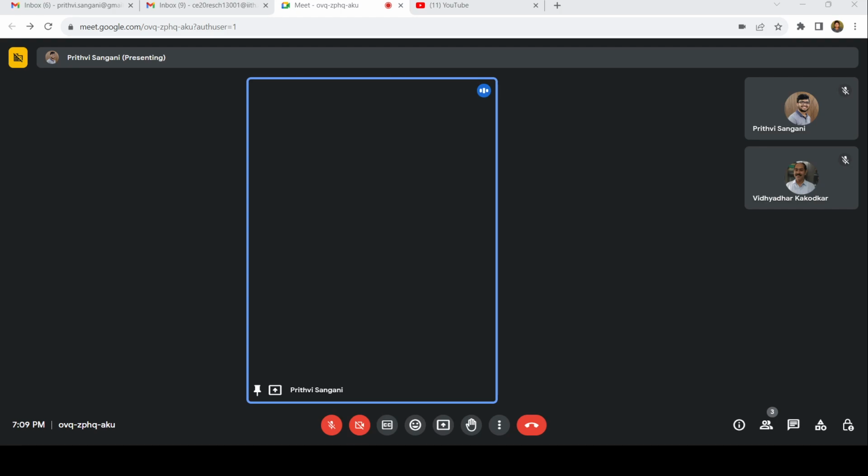Now what is our delta 1? Delta 1 is nothing but sigma fi ui li by AE, right? So with this, we find delta 1 is minus 54.14 by AE. What about delta 2? Delta 2 is going to be FBE times sigma ui square li by AE, and that is going to be FBE times 4 plus 4 root 2 by AE.